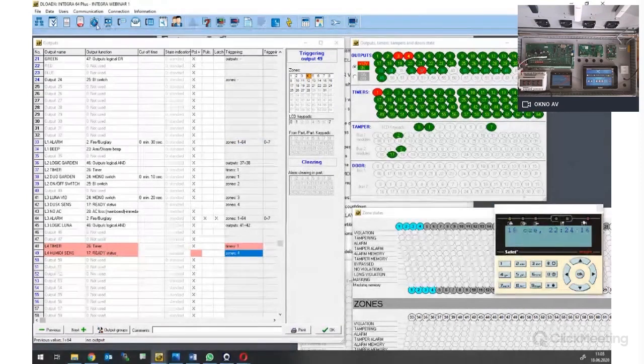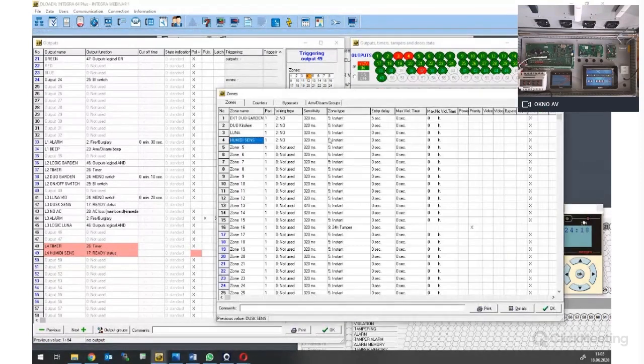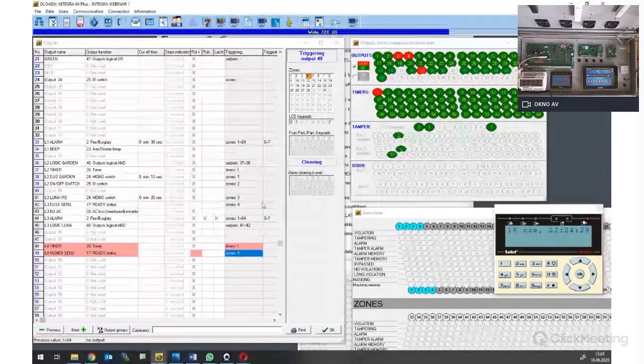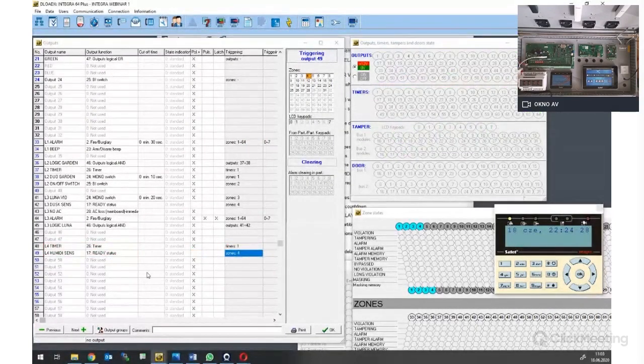One more thing, if I'm using this type of sensors, I would never use zone type. I will use 47, no alarm action, okay? So there is no alarm. I don't want to know if it's raining and there is alarm in there. So this is the second part of our logic.